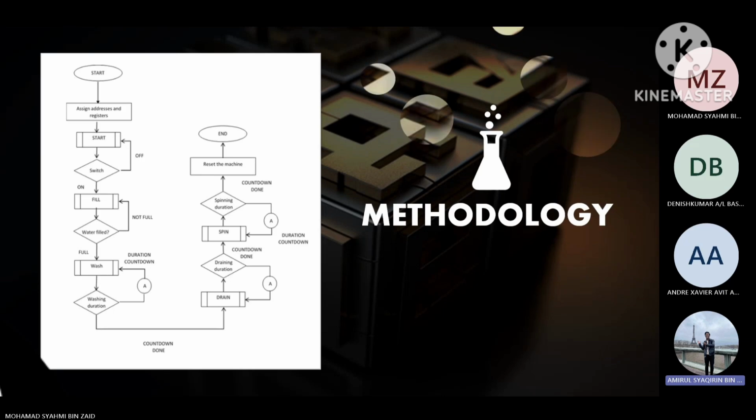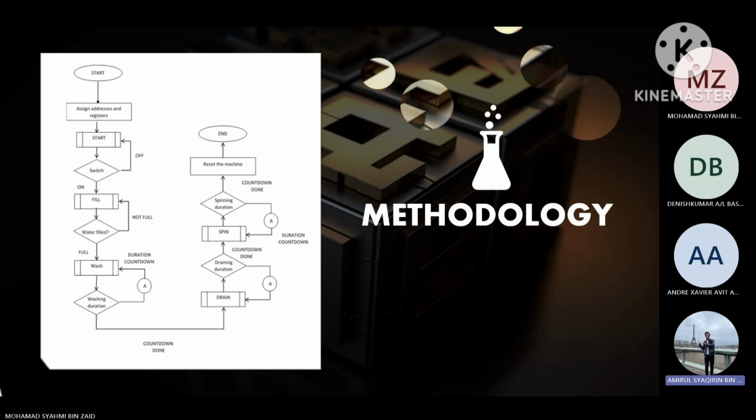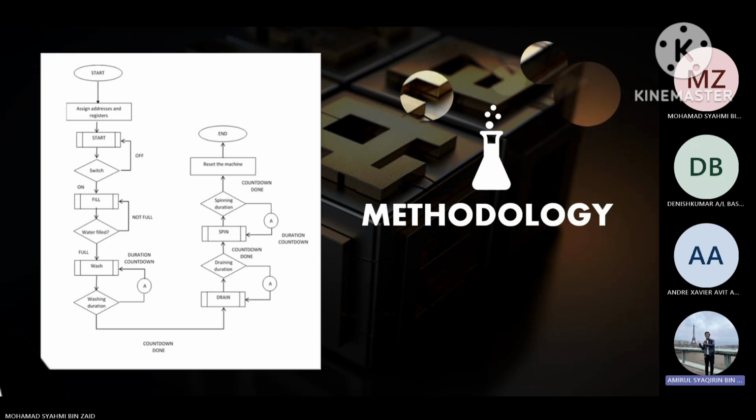When the countdown duration is done, the software goes to the next routine, which is the drain subroutine, and the operation of the motor here is represented by the LED for the purpose of simulation. The next step, which is the 8th step, the software goes to the drain subroutine, which shows drain in the 7th segment. The duration of the draining has also been set in the start subroutine and is called by the address D6.